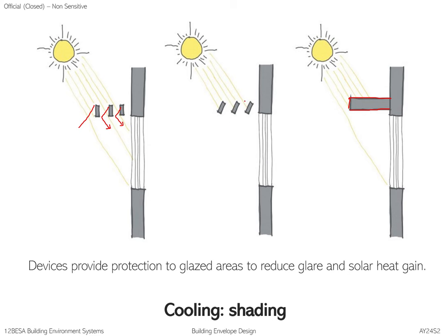In the second instance, same spacing, same profile, but just by tilting the angle, you notice that it cuts out the direct sun's rays, which no longer touch the glazed areas directly. It's all via reflection already. So the effect of light that you get is diffuse. These two instances, same spacing, same profile, just different angle, different quality.